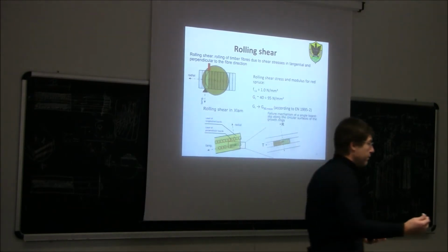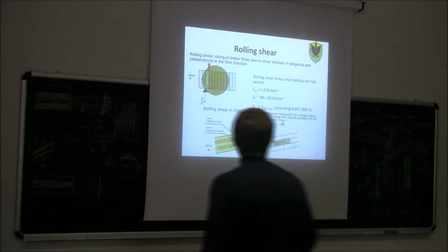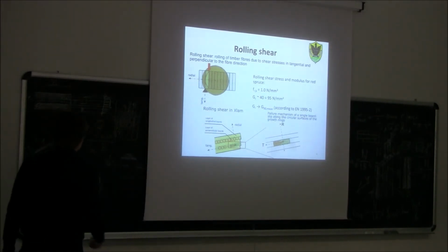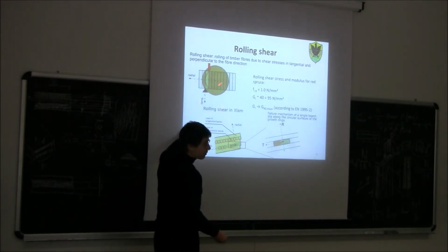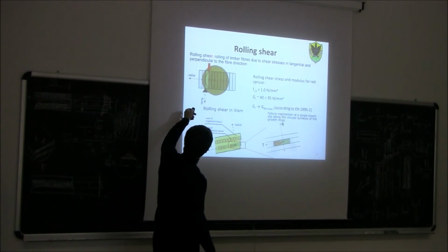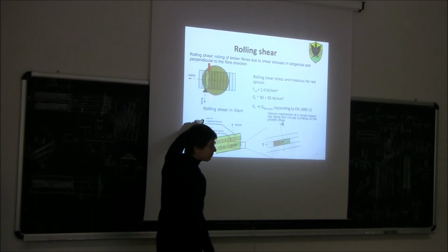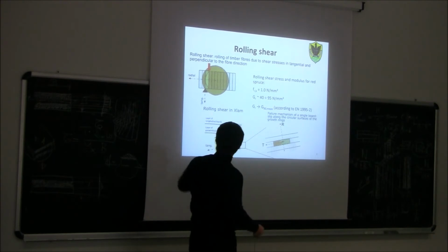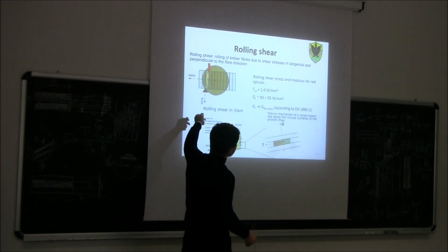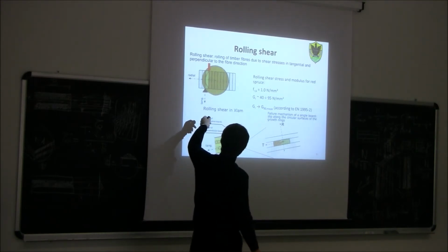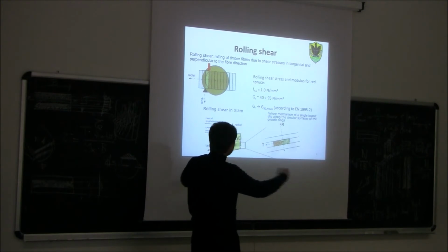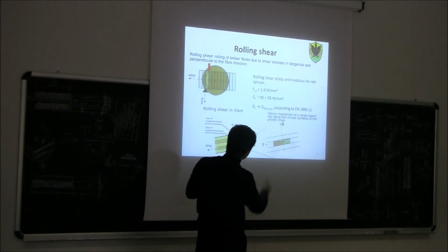So in other words, if this is the trunk, so this is the load, if the shear plane is parallel to the tangential plane, like here, this is going to cut directly only the middle lamella, and the shear strength is much lower than if we have a shear plane oriented along the radius. So in the other plane.